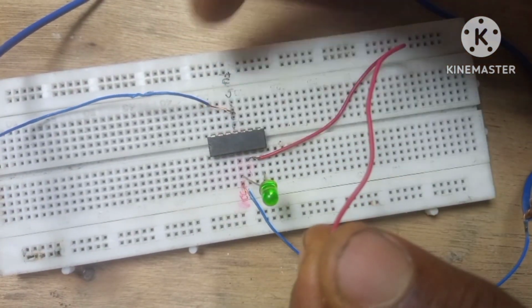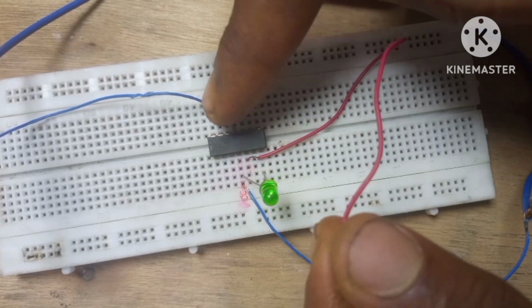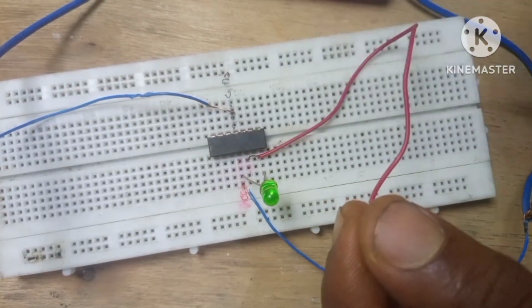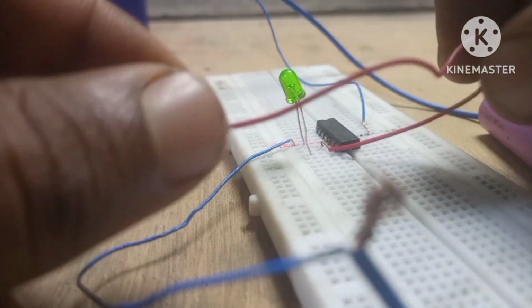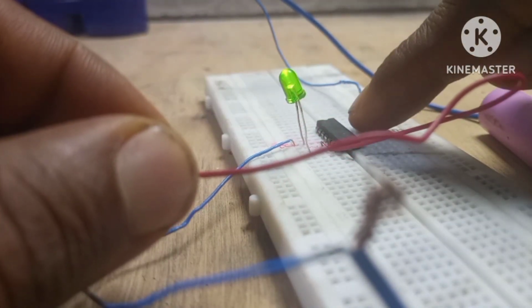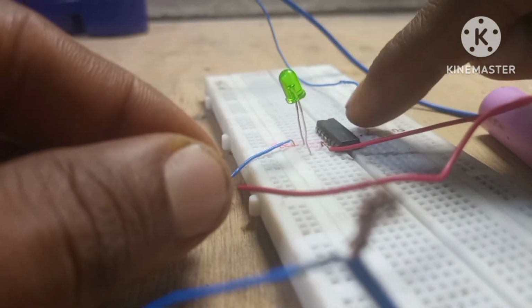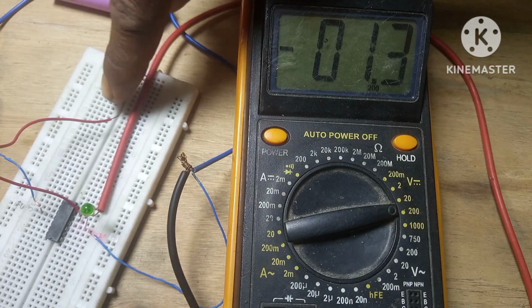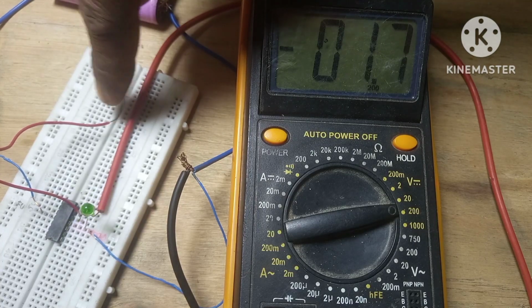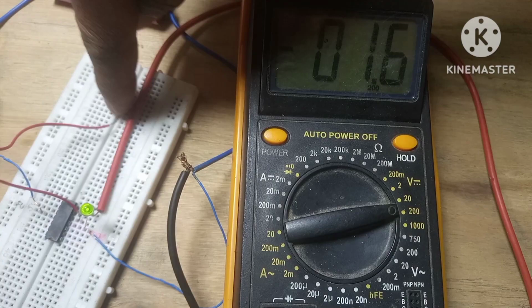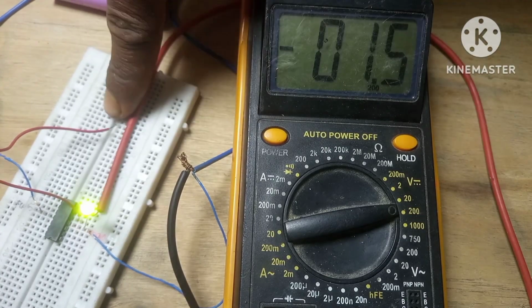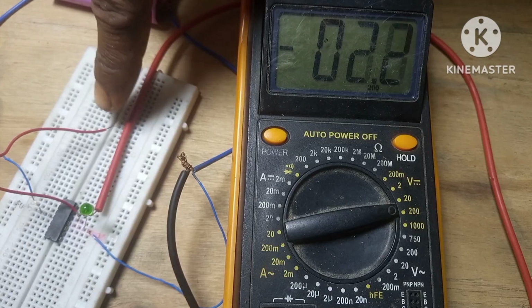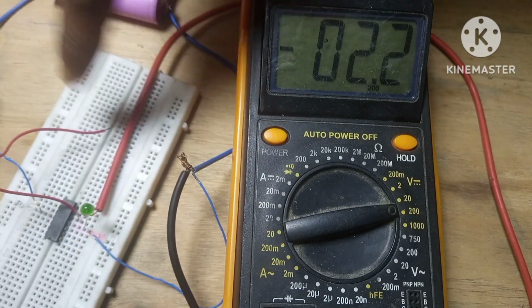This technique won't work for all ICs. Some ICs get triggered by a small amount of voltage from a power source, while some ICs get triggered by electrostatic charge. You can also turn your meter knob to the DC voltage mode, then connect one probe from the multimeter to the IC negative pin, and then use the other probe of the multimeter to test each leg of the IC while pulsing it with a finger. You can experiment on any IC with this technique. This helps to study the IC behavior.